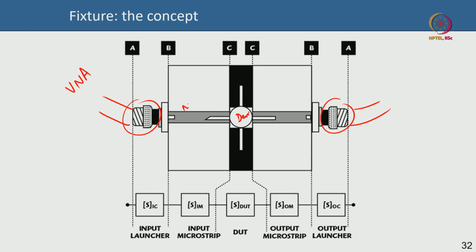Okay, these are microstrip lines. Okay, these are printed on the board. The white thing you see, that is like your board. It's often an alumina substrate, a low loss alumina substrate. Below that there could be a board, a metallic board or whatever, and then it enables you to basically bring the RF signal, okay, and you can measure that and it can come out